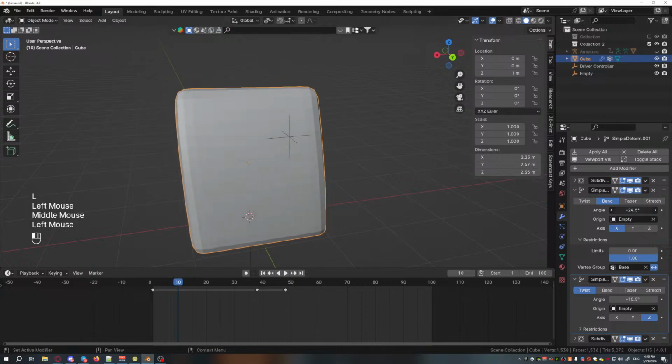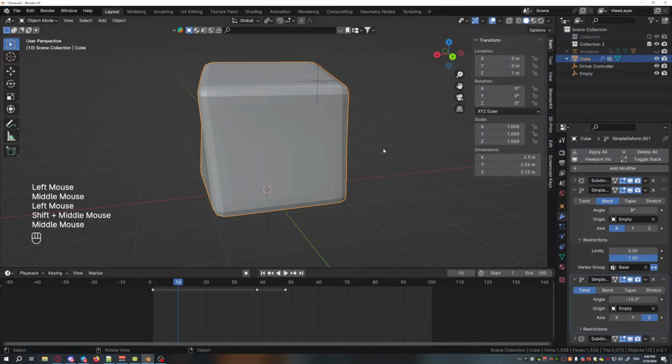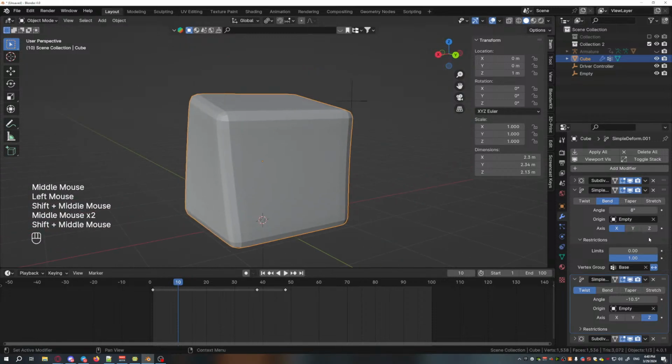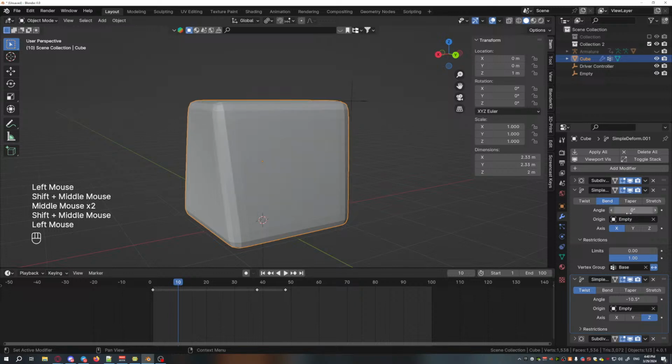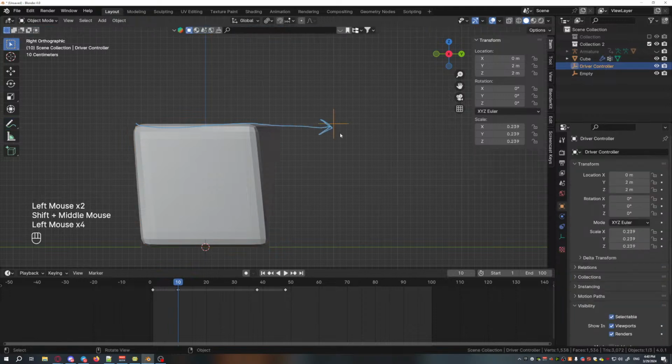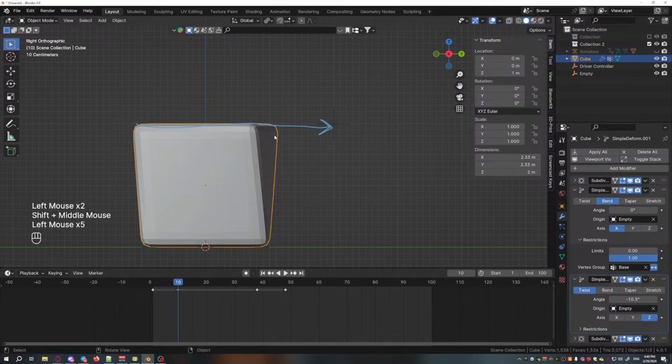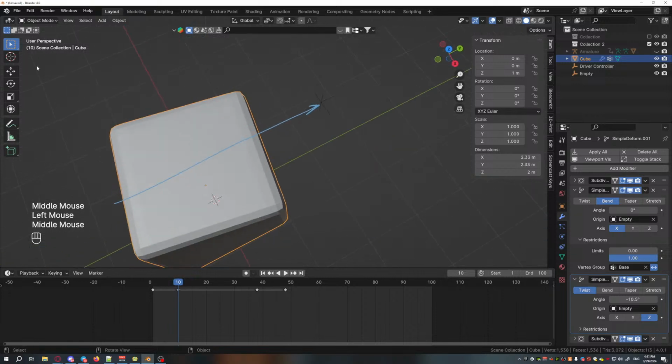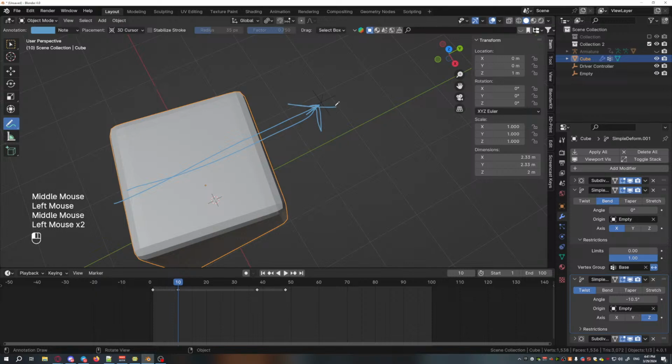So this thing tilts the top of the cube. So what we want to do now is to make it so that this cube looks at the proper height of this object. Now that you have seen how drivers work, I would ask you to help me make a proper driver for animating this cube, so that it looks with its top part to this empty object.